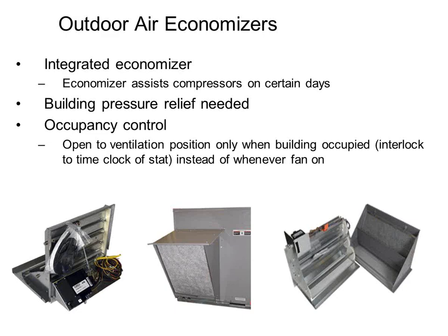But if I just have a 1 or 2 stage fan, then I'm going to go with the switch idea. When I get to a certain position on the damper, a switch kicks on and turns on one of the stages of power exhaust. Right? So if you can get the building pressure sensors going and you have a unit that's large enough to have a VFD option for the power exhaust, that's great. All right, so continuing on.